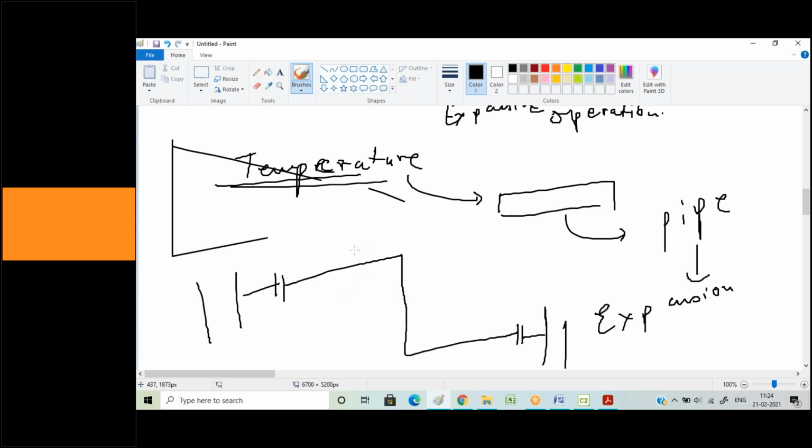Okay, so now when I'm saying that this particular line is going in this direction, then it's coming down and getting connected to another piping. The temperature for this line, let's assume it's 400 degrees Celsius. At this temperature, the material of the pipe, let's say it's SS316L, will have a certain amount of expansion.